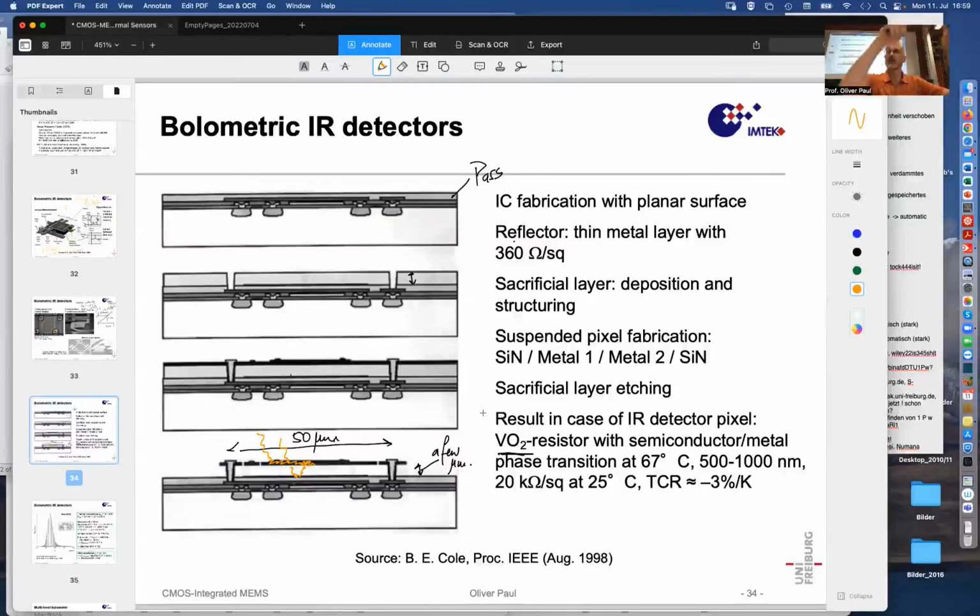And then you may know that the top surface of silicon solar cells is structured. It's etched like little inverse pyramids. And then the light that is coupled through gets a chance to cross the silicon for a long time, and then a second time for a long time, and then it would get out again maybe, but because there is some inclined wall, it is reflected back and forth many times, and then you get another % of efficiency out of the material.